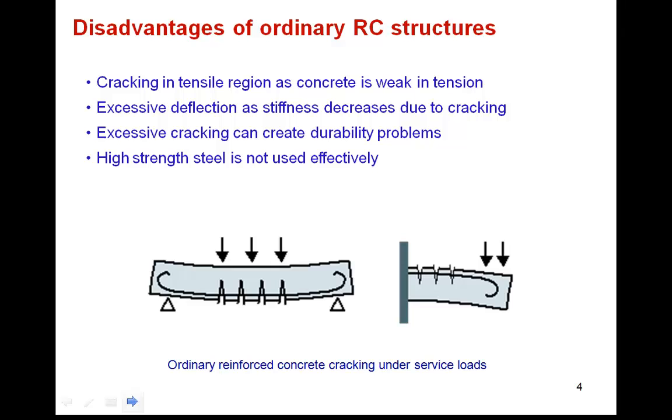When the concrete cracks, it reduces the effective area of the concrete which contributes to its moment of inertia. The reduction in the moment of inertia means the deflection will increase because the stiffness has reduced. Also, excessive cracking can be a durability problem as well.